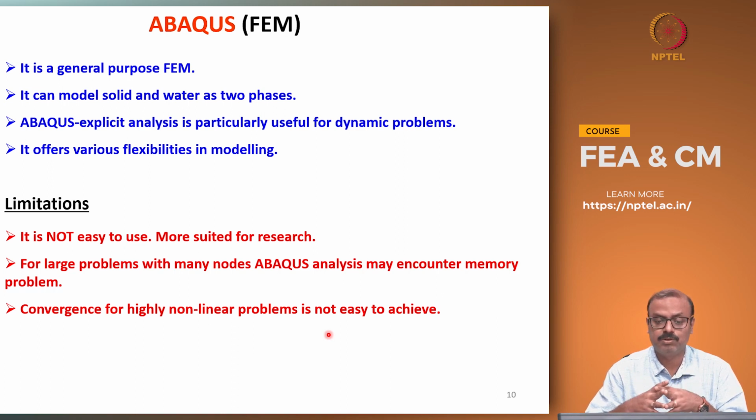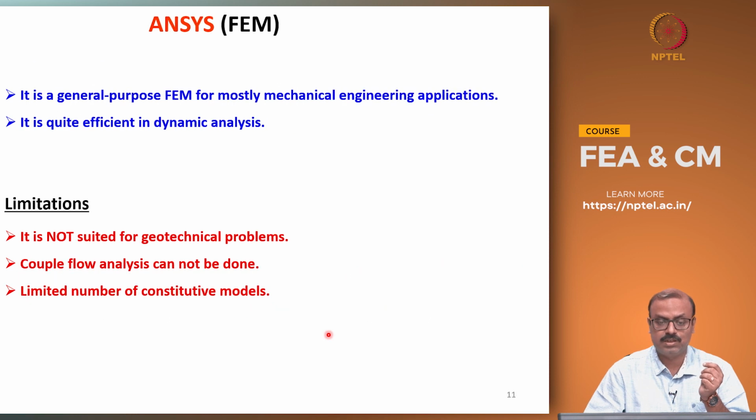So you can do effective stress analysis, but one of the drawbacks of Abaqus is runtime memory. If you require more, then sometimes Abaqus analyses are not so efficient in terms of the running time and the computational cost. So that's one of the reasons why Abaqus is not so popular in industry.